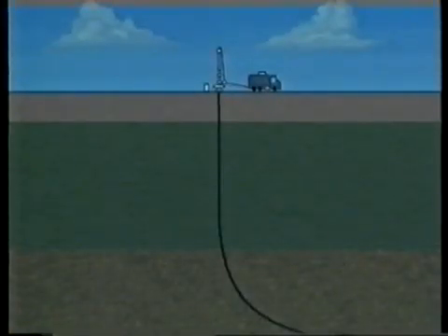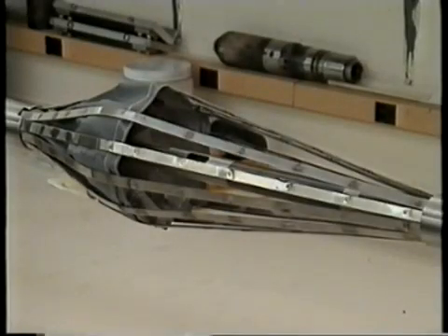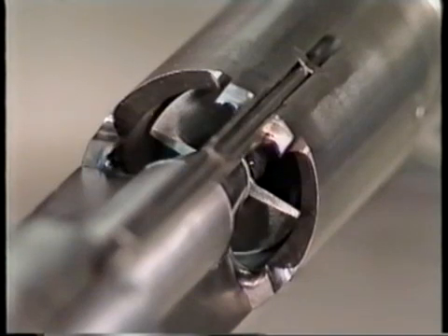Deviated wells with multi-phase production pose a unique problem because the oil or gas tends to gravitate to the pipe's high side and the water slides down the low side, giving the appearance of downflow. This problem can be minimized by the use of a diverter-type flow meter, which expands an element to force the flow through a funnel-shaped test section. The response of the diverter flow meter is pre-calibrated, and each tool and spinner combination has a unique calibration curve obtained from the vendor. Often these tools also contain a fluid identification device.